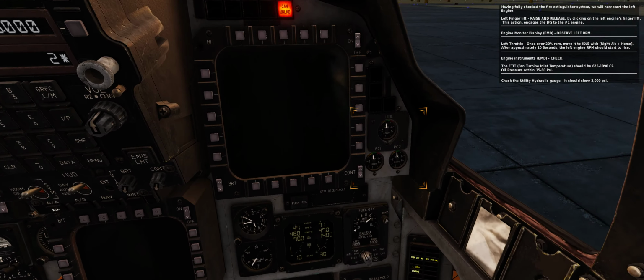MPDs and MPCDs, turn on. A 2-position rocker switch provides electrical power to the displays. When cold starting, the aircrew must turn on the displays. However, if the aircrew experiences a brief power interrupt in flight, the displays will automatically come up, without needing to use their switches again. HUD and UFCP. Set to on, by turning their brightness knobs clockwise. We already did this for the UFCP on a prior step, do the same with the HUD.